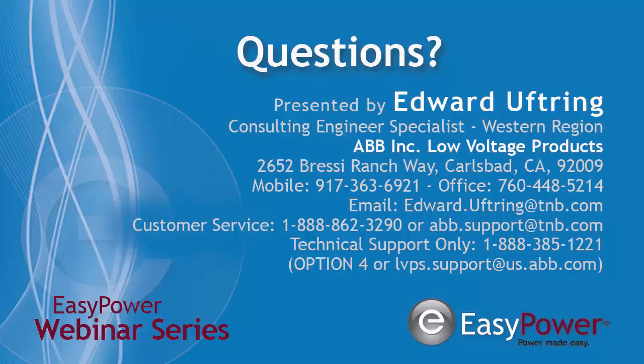Series rated breaker is a little bit tricky because when you're doing a series rated breaker, to get the ratings you actually have to run the test. So series rated breakers don't come out with a series rating. We do have a comprehensive list of all the tests that we have. So there are part numbers. We tell you exactly which series are rated and how they're rated, and the D rating as well. That will be on the website, and again, if you can't find the information, any CES or application engineer at ABB will be glad to help you with that.